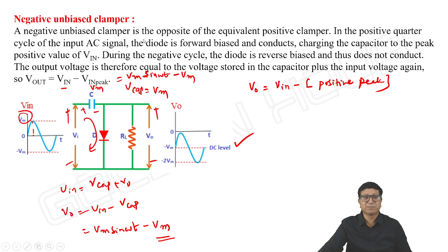Negative clamper. Negative unbiased clamper is the opposite of the equivalent positive clamper. In the negative quarter cycle of the input AC signal, the diode is forward biased and conducts, charging the capacitor to the peak negative value of input. And during the positive cycle, the diode is reverse biased and does not conduct. The output is therefore equal to the voltage stored across the capacitor plus input voltage. Okay, voltage stored across the...